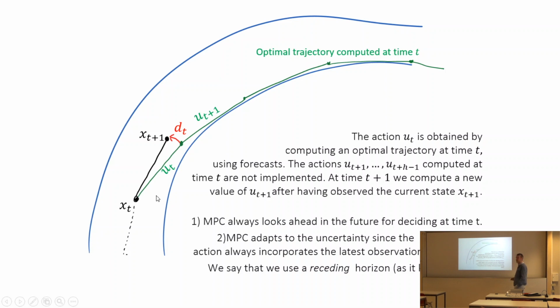So you implement this, you think you would do this trajectory, but then perhaps there is some wind or some bumps on the road so that the trajectory is not exactly where you want it to be. Perhaps also there is inaccuracy in your model. When we're engineers and we use MPC, we are never sure that we have 100% accuracy of the model. I mean, 100% accuracy of the physical world is very hard to get.